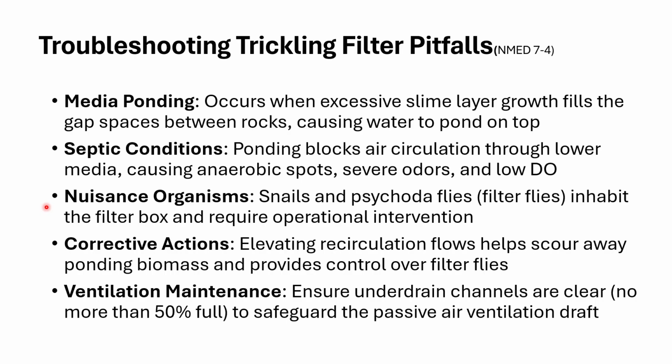Then you're going to have to start all over again building up that snot layer or that film on the media. And one of the short videos that I have in your YouTube videos shows you an example of red worms and snails inside an RBC, but it's the same concept here. Those are nuisance organisms. You do not want those to start popping up in a trickling filter.